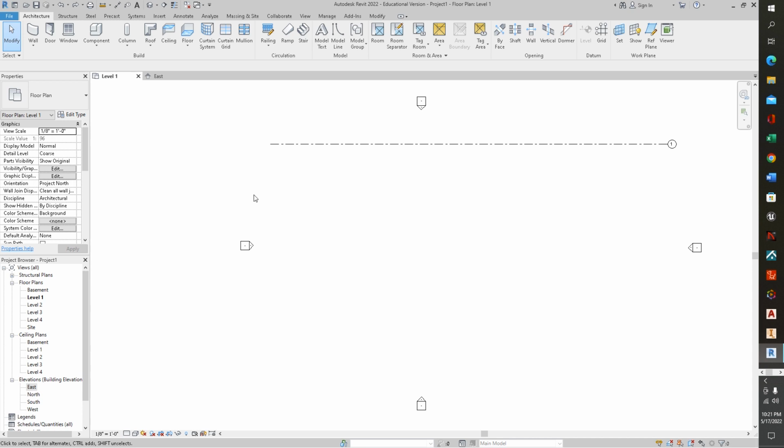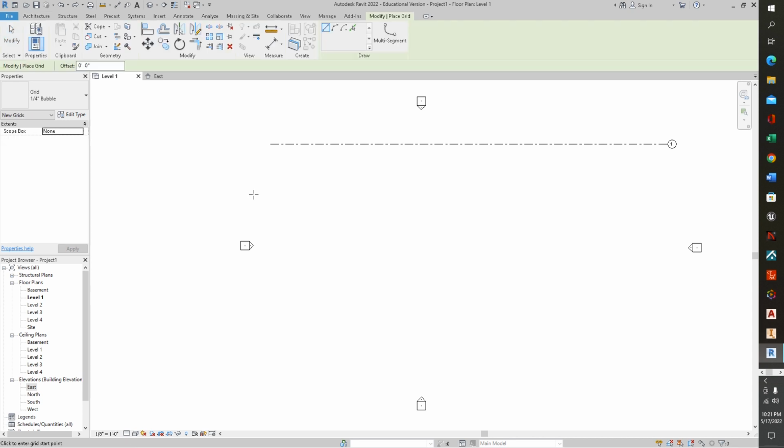And we'll open up our grid lines command again with a GR that we're going to type in on the menu. We could draw in another one. As I said, we could draw in and it's going to go the other way. We could do that, but we want to have more precise lines than that, a little bit more control. You can change the direction of this too if there's some reason why you wanted a grid line to go on at different angles. Certainly you could do that.